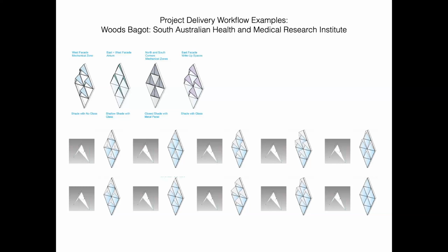So here you can see that the shading devices could be much deeper, right? Or they could be very shallow. They could almost close things off, or they can move upwards, right? And so this three-sided pyramid can move around, and can also become deeper, stand off further from the facade, or get much closer to the facade. And what that does is allow you to fine-tune each of these panels for how much view you can let out, how much privacy you need from outside in, and how much shading you need from the sun up above.